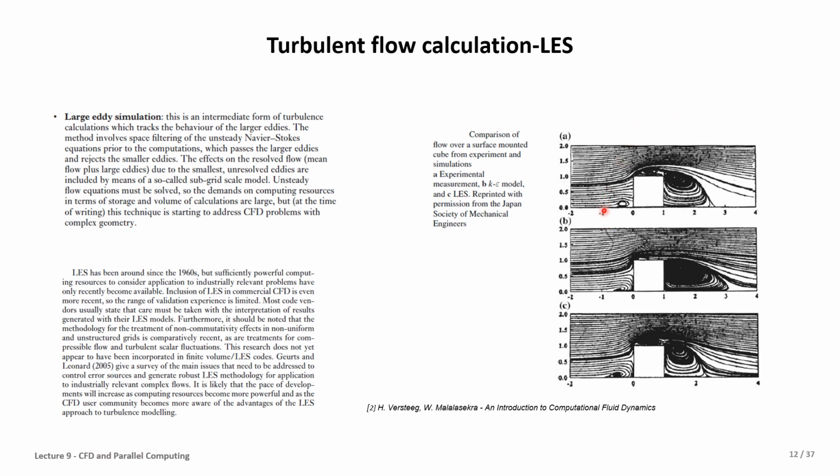Here we can see in this area, and here, it presents a different result. Also here, when the flow reaches the object, it behaves differently. However, in general, LES presents results better than RANS. Here we see in B, the RANS solution has many differences, and it presents only the mean properties. From this example, we can recognize the difference between LES and RANS, and of course, LES presents a much better result.